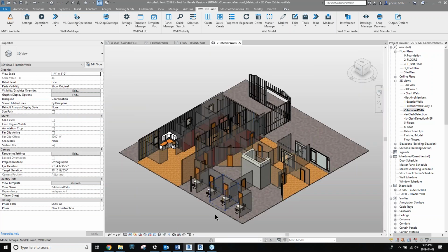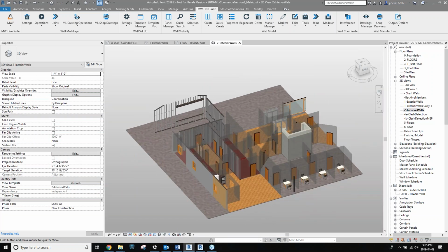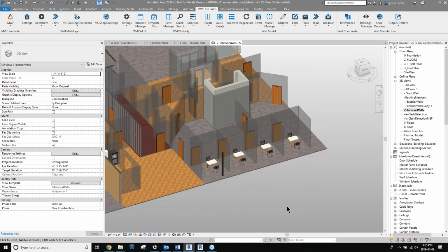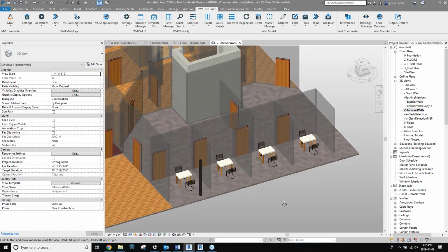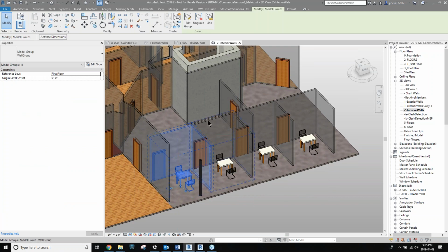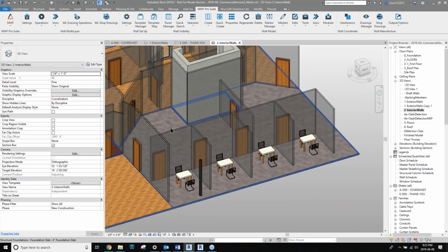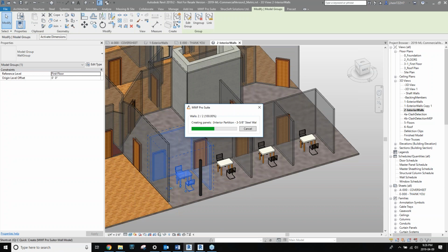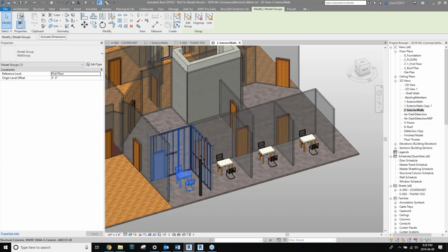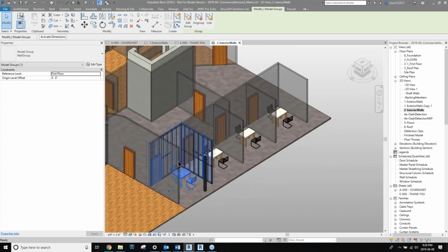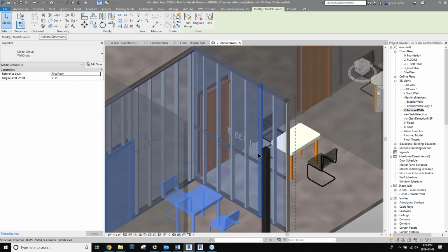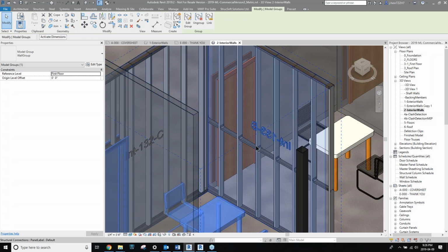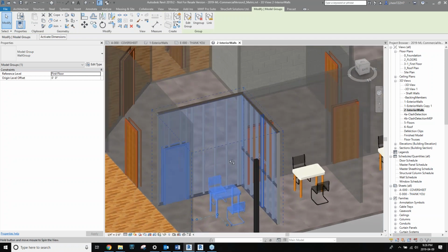We'll close that one. So I have a nice 3D view here with some transparencies on again. In a lot of building now, if we have repeatable units that happen to be in model groups, we can handle the framing of these model groups. Just grab the model group, whether there's a door or furniture in it, and if we do our quick create, which I set up a shortcut key of QC, it will then parse this model group and only look for the walls, and it will frame the walls individually. I do get new tags on them that are individual for the item.